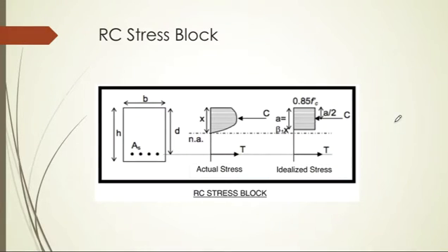So here is our reinforced concrete stress block. So right here we have the compression of the concrete, and this is assuming cracked, but we'll get into that soon, and the tension of the steel and the lever arm between. So that's where we get our moment capacity from.